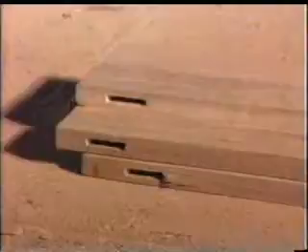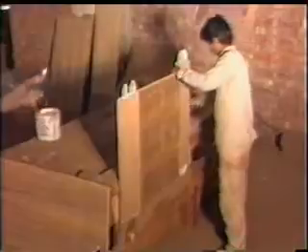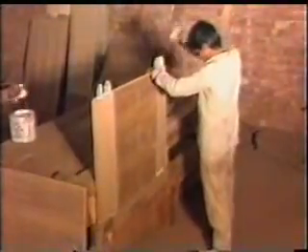Moisture content should be within 8 to 14%. Stiles and rails should be one-piece members and are joined to each other by mortise and tenon joints. Ensure that rails are not of through type but are 25 millimeters short of the width of stile. Joints are glued by good quality synthetic resin carpentry glue.